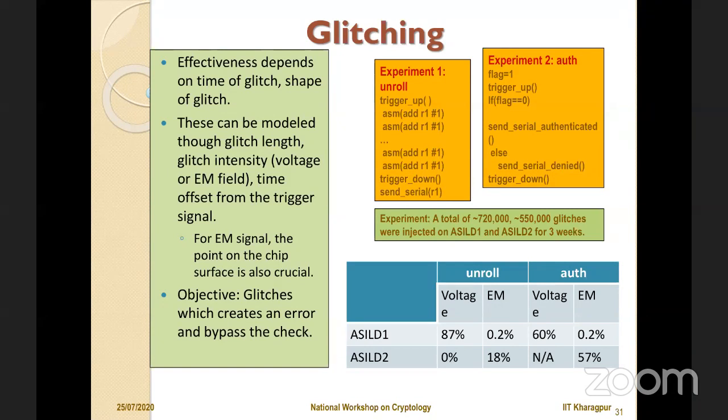But if there is a fault, and the fault essentially, say, bypasses an instruction, or rather skips an instruction, which is very common, by the way. If you take an EM gun, then you often see that either the instruction is skipped, or in some cases the instruction is modified. Suppose you are doing a multiplication, the multiplication probably ends up doing something else. It doesn't do a multiplication, but maybe does an ANDing operation.